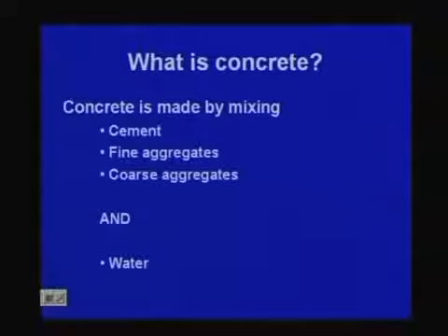If we add less water, the strength of the concrete will vary, and if we add more water, the strength will also vary. So, water plays an important role in concrete making. We describe this as the water cement ratio, which tells us whether the concrete will achieve the target strength.